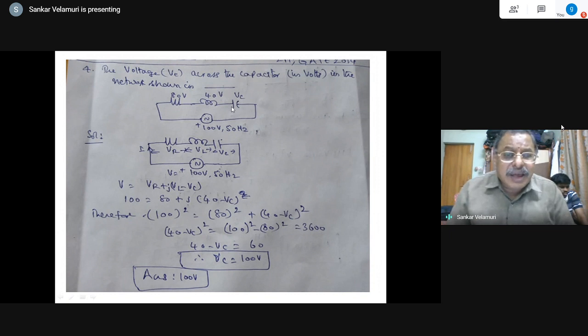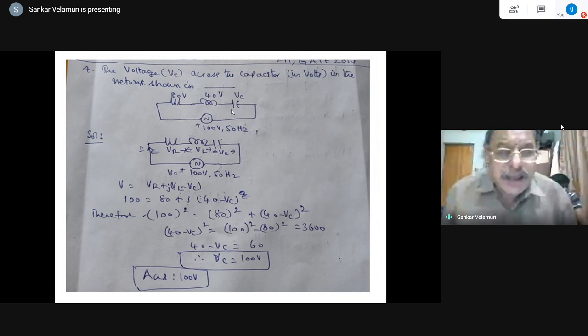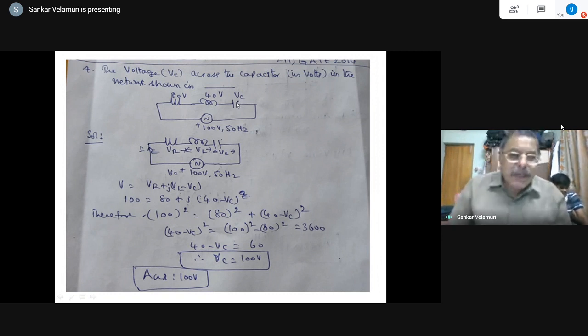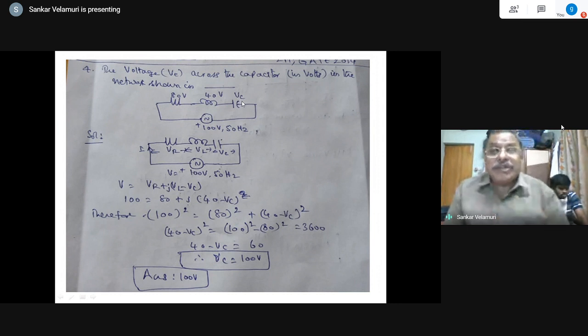Okay, the capacitor ideal value has an inherent parallel resistance. That is a typical concept. Most of the times the shunt resistance, the internal resistance of the capacitor, is negligibly small compared to the inductive circuit where the internal resistance is taken as series. Nobody explains this most of the times, but this point is to be understood carefully, because when I talk about internal resistance, when both components are there, what about the internal resistance of the capacitor? Internal resistance of the capacitor can be treated as shunt resistance, but that can be treated as very, very negligibly small. That means it offers almost infinite resistance to the circuit behavior because capacitance is predominant in that.